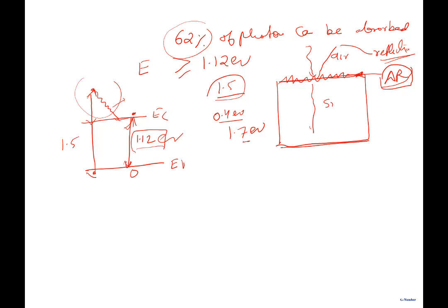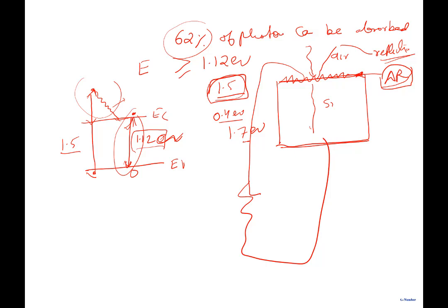Now the issue is, this is the internal energy of what you are left with. You can take as a reference 1.5 eV is what you absorb, but you're left with 1.12 eV. But how much energy is the solar cell able to deliver to a load? It's the voltage that is able to develop across the load. Voltage is related to energy.